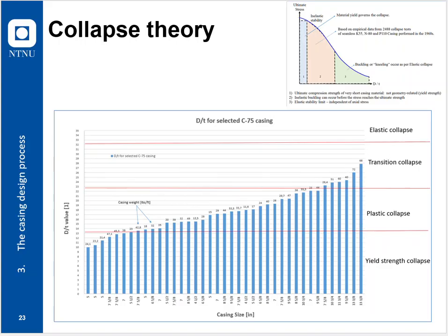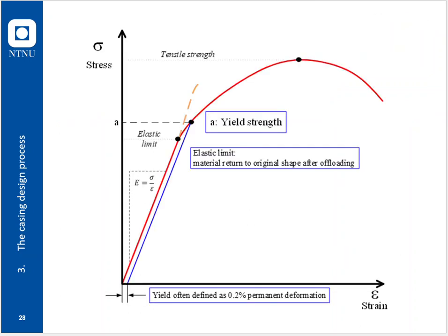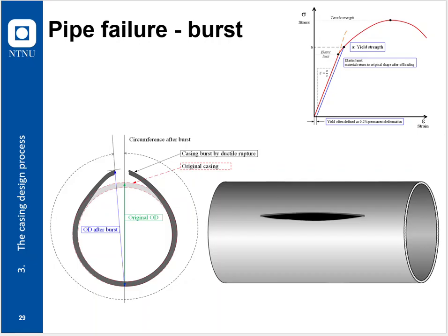It is mathematically correct, more or less by accident, as it says in the standard. And you're trying to tie that to this point that is not so very visible. That's why I'm saying burst is not as easy and straightforward as collapse, whereas 90 to 95% of the pipes are governed by this type of visual failure. I'm probably more clear now than when I started out trying to explain this.